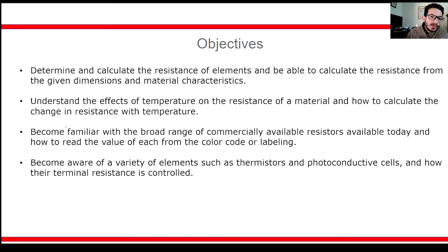So the goals are to know how to determine and calculate the resistance of elements and to be able to compute the resistance from a certain dimension or geometry. So in this particular part, when we talk about resistance, we have to take into consideration the length, the diameter, the material. This part is dependent on the geometry and the material. So one of the main goals is to know how to determine the resistance of a material, knowing the geometry and knowing the material. Also, we want to understand the effect of temperature.